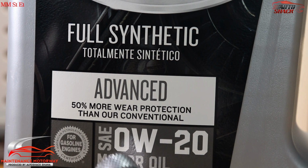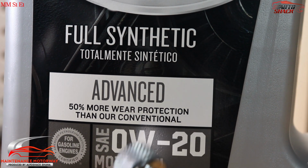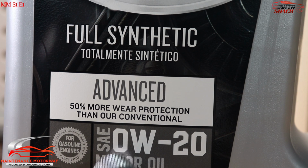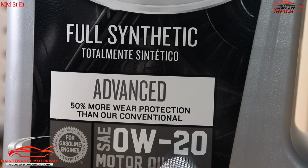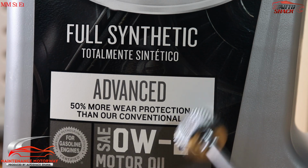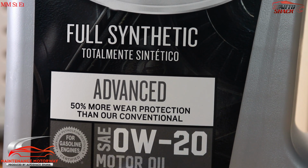Now, there are actually 11 official viscosities per SAE standards. SAE stands for Society of Automotive Engineers, and it's also a regulatory body that basically sets these viscosities, among other things. There are 11 official viscosities: there is 0W, 5W, 10W, 15W, 20W, 25W, and then there is 20, 30, 40, 50, and 60. What you're looking at here is called a multi-viscosity oil because two different viscosities have been combined into one.